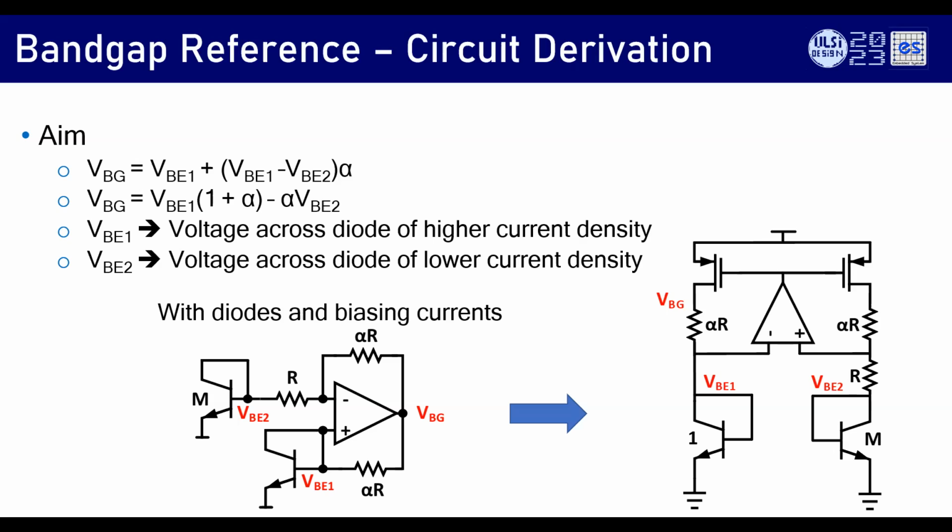These are the most commonly used bandgap architectures. For simplicity, I drew NPN, but it can be a PNP diode. It's not a problem with 1:1; I just retain the same convention. This is the high voltage bandgap used for a lot of years in many chips and silicon, and it is a very popular one. More or less, every bandgap architecture you see has a bandgap core. This is also called a bandgap core, and we use that only.